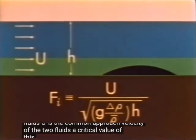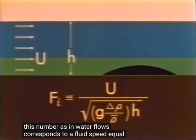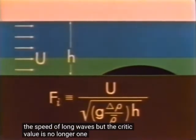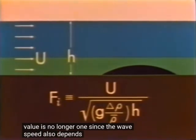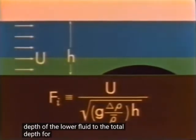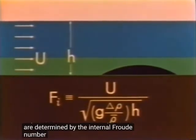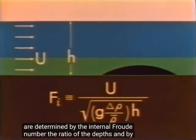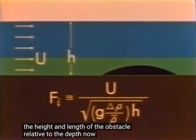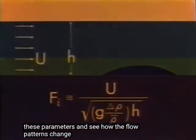A critical value of this number, as in water flows, corresponds to a fluid speed equal to the speed of long waves. But the critical value is no longer 1, since the wave speed also depends on the ratio of the depth of the lower fluid to the total depth. For two fluids, the flow patterns are determined by the internal fluid number, the ratio of the depths, and by the height and length of the obstacle relative to the depth. Now we will vary these parameters and see how the flow patterns change.